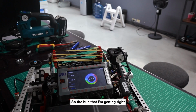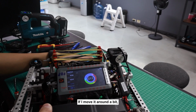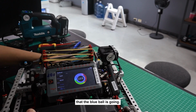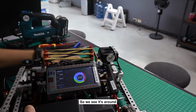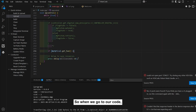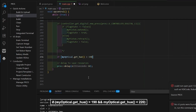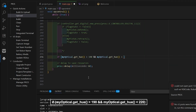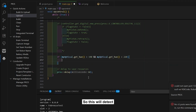So the hue that I'm getting right now is 211. If I move it around a bit, I could see the lowest and the highest hue that the blue balls give. So we see it's around 190 to 220. So when we go to our code, we can put, if it's more than 190, and this is how you put and, my optical.getHue is less than 220. So this will detect balls in the blue color range. So if blue, run this code.